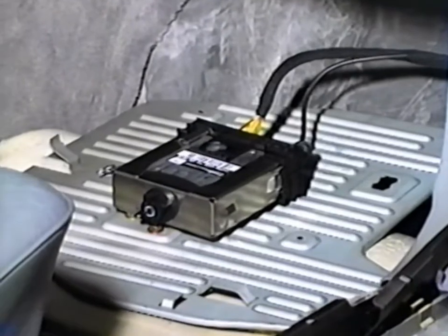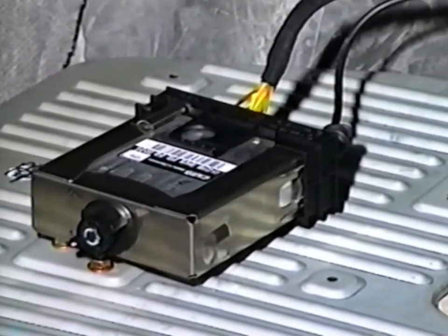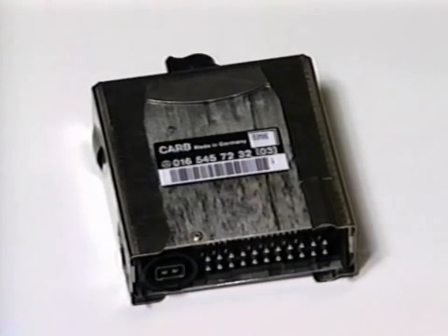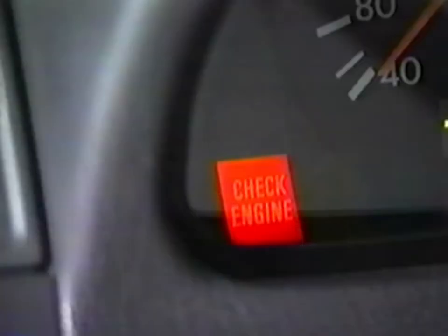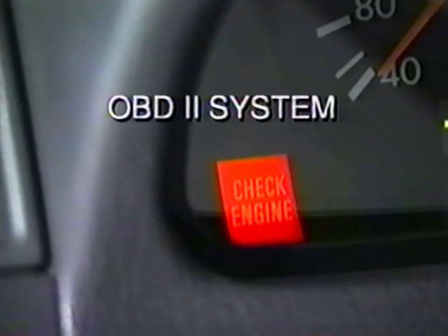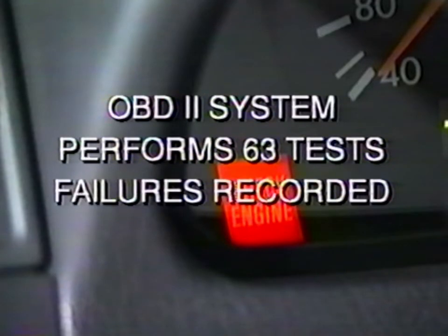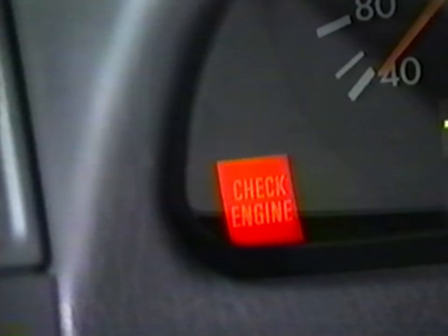Onboard Diagnostics 2, which in effect refers to the diagnostic module N59/1, is a substantially expanded version of OBD1, as used on 1993 model year vehicles having a check engine light. With the OBD2 system, a total of 63 tests are performed, and failures are recorded if they meet certain predetermined conditions. If the recorded failure may be critical to vehicle emissions, the check engine lamp is activated.